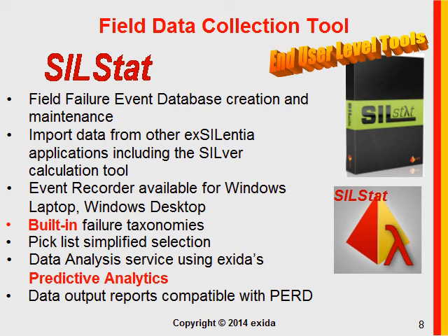SILSTAT, in a little bit more detail, the objective is to record field failures and store those in a database that we can use to further evaluate our original assumptions. So when we do the analysis work, when we do the realization work, we assume certain probabilities of failures, we assume certain demand rates, and the objective of the SILSTAT software is to record those events and then allow us to compare our actual performance with our assumed performance.